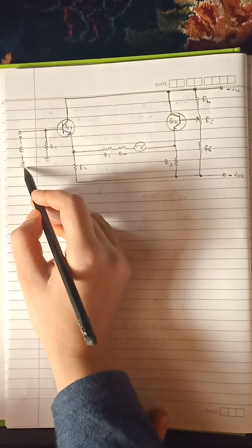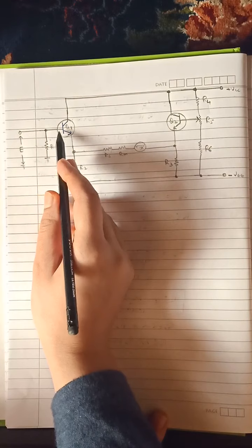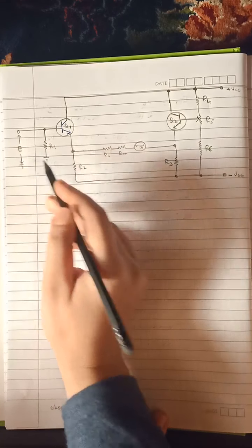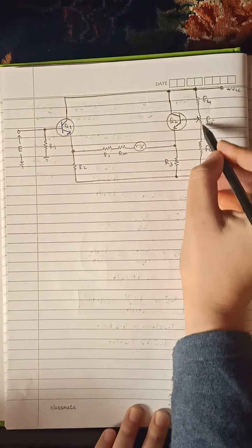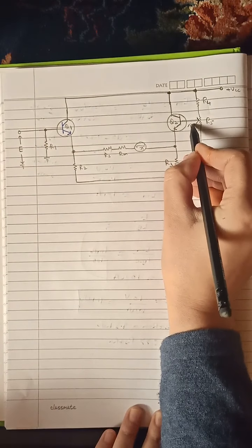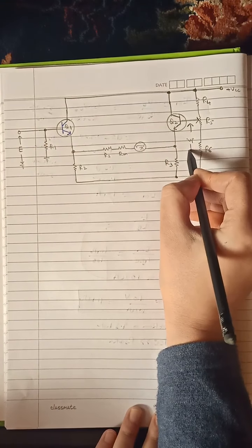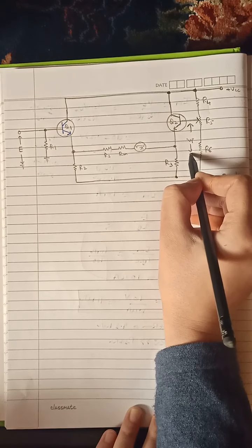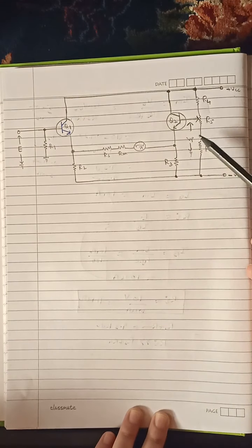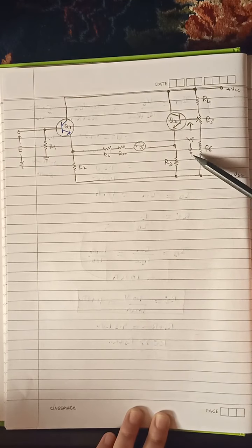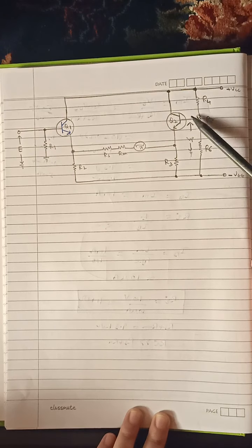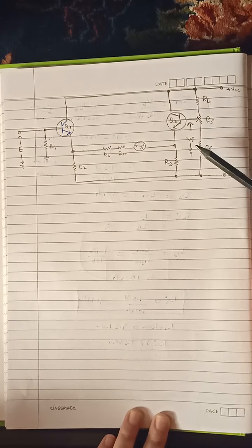So that means the input voltage E, which we have to measure, is connected to the base of transistor Q1, and this potential divider provides the voltage VP, which is also grounded through this. In order to keep the bias correct, we should always connect it to ground, or the voltage across this should always be equal to 0.